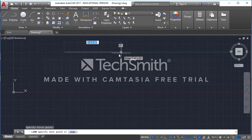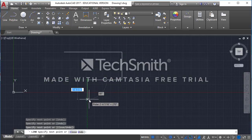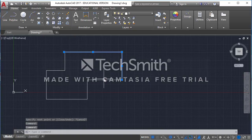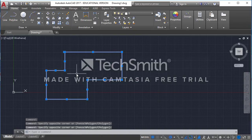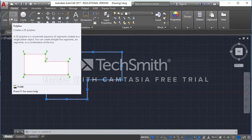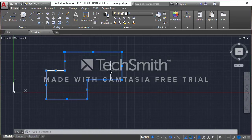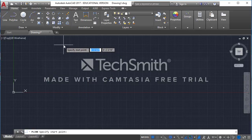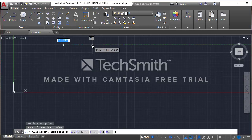If you notice when you use the line tool, and I'm going to create a bunch of different lines here, we'll pretend this is our house. Notice that all of my lines are individual line segments. That is the difference between using the line command and the polyline command. Polyline is one long continuous line, whereas line is individual line segments. The nice thing about the polyline is that if I know the perimeter of my building, I can quickly outline it.